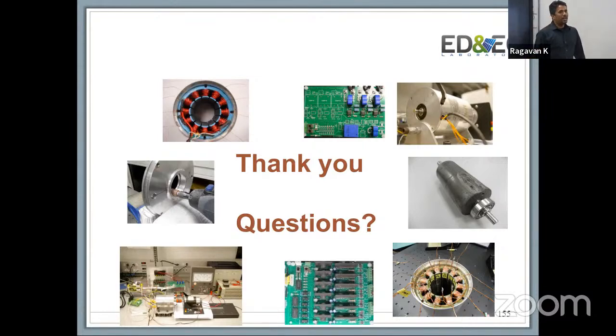So if you look at the idea for sensorless methods, in fact, some of the work when I was a student, there was this work on delta hysteresis modulation, where they looked specifically at the idea of removing one sensor at a time. And they took it all the way down to only one sensor. Instead of 3, which is obviously an overkill, you have redundancy. 2 is enough. It is the number that normally we go for, but they also took it down to one single sensor. And they were trying to do what's called delta hysteresis modulation.